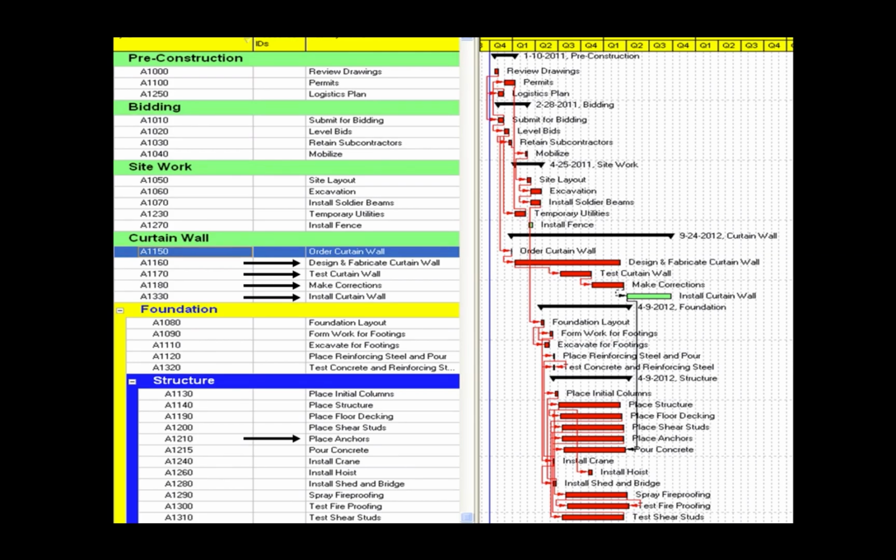So I've seen times where those anchors hadn't been placed when they should have been, or one out of the two anchors were placed in certain locations. And to correct that is very difficult. You basically have to drill through something you've already built and make a connection. Usually using some kind of epoxy now, because you can't go right down into the steel, because you don't have a bottom nut to it. Or you could go up from the bottom and the top and do it, but that's even further. So you use some kind of epoxy joint with an expansion anchor. Not perfect, but it's a way to solve a problem if you have it.